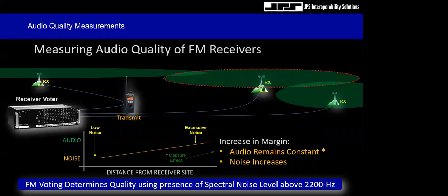But for the most part, the nice thing about FM communications is we're modulating and demodulating the system with respect to the instantaneous frequency of the carrier. And we take that information and send it through a superheterodyne receiver, and we're going to deconvolute that information and extract the baseband analog audio, which is going to be our speech or music coming from